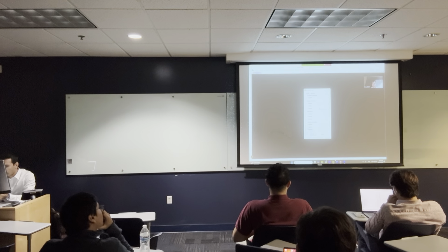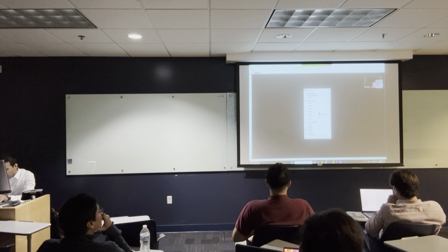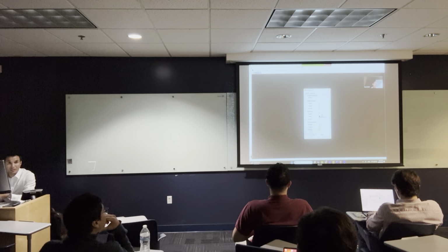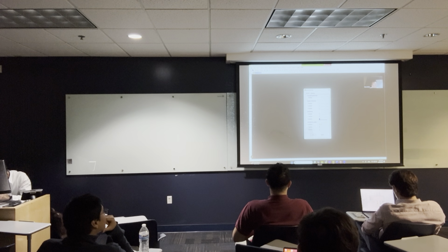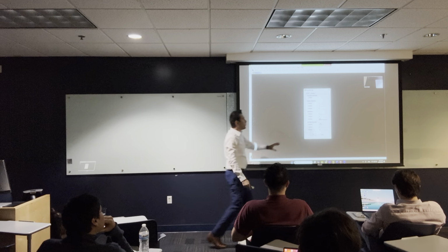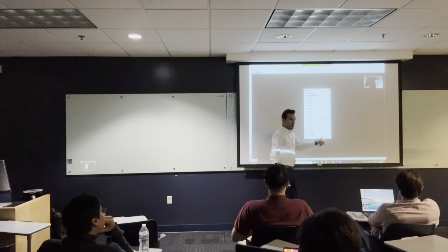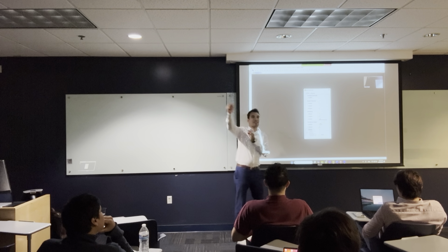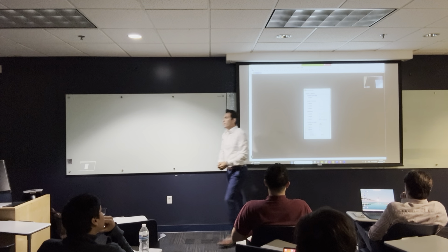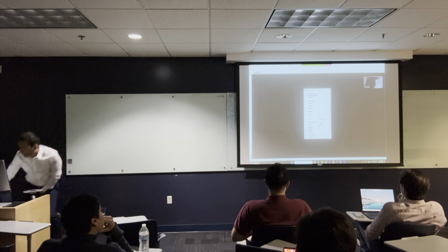I do a 3. Here it doesn't matter if you put 6 or 10, it's only one grid. And here I'm going to put 4.4. It says, where's the grid line location? Basically, the last one is asking you, do you want the grids to start from 0, 0, 0, the origin, or do you want to put them at a specific origin? No, I want them to start from 0, 0, 0. So then I'm going to hit OK.